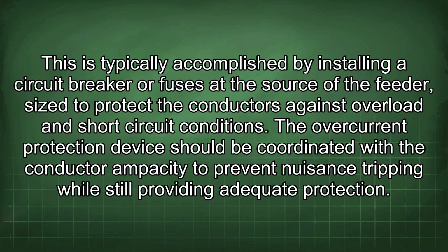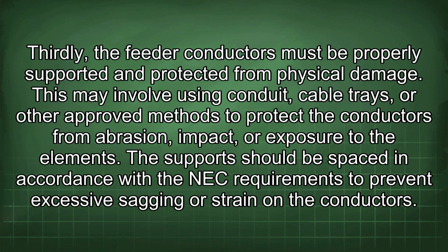The overcurrent protection device should be coordinated with the conductor ampacity to prevent nuisance tripping while still providing adequate protection. Thirdly, the feeder conductors must be properly supported and protected from physical damage. This may involve using conduit, cable trays, or other approved methods to protect the conductors from abrasion, impact, or exposure to the elements. The support should be spaced in accordance with the NEC requirements to prevent excessive sagging or strain